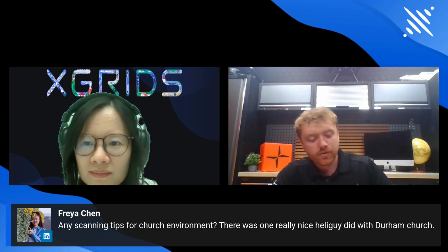Yeah, I mean, usually when we're doing surveys, I try to avoid the need to go back to site again. I want to do it there on site in the day, so as many images as possible with the drones. Our experience has mainly come from following the tutorials online and what XGRIDS have. So four different takeoffs with the Matrice 4E, and as you're going up with the drone, tilting the gimbal towards the ground until you reach the altitude that you're doing the mapping mission.